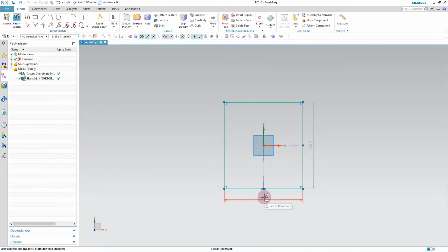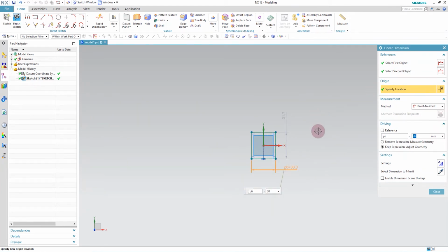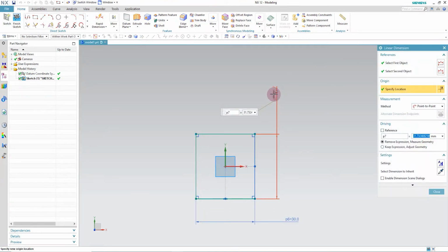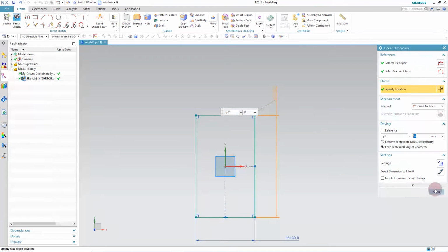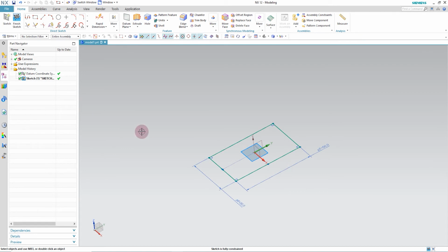And in this case, I'm going to change the cross section a little bit different. In this case, I'm going to use 30 millimeter by, let me just do it, 50 millimeter. Okay, so this is going to be the cross section of our through mortise and tenon joint. Okay, so I'm going to extrude it.